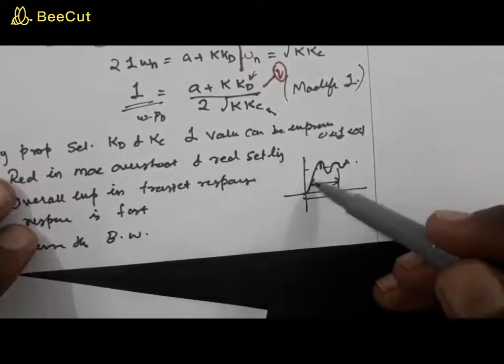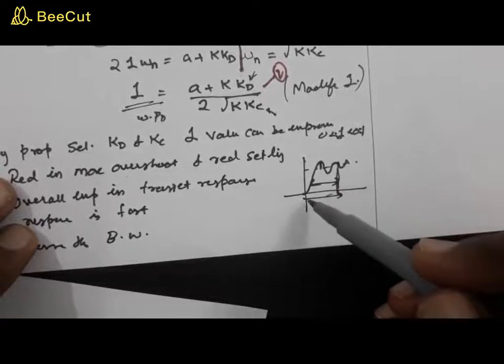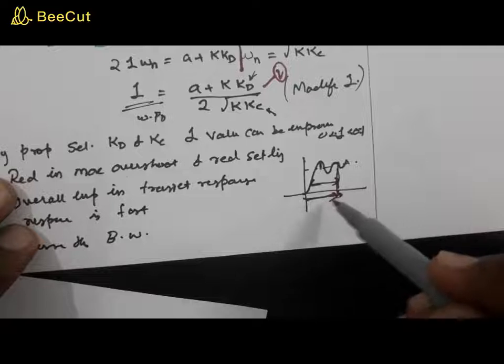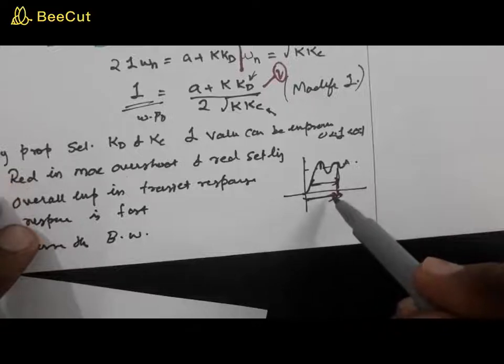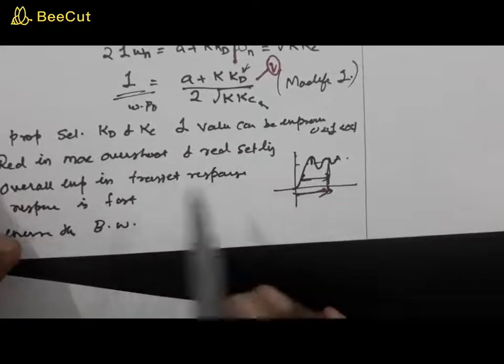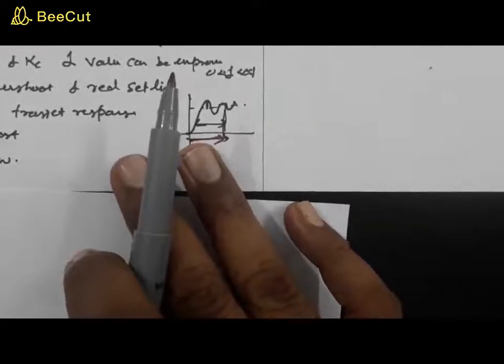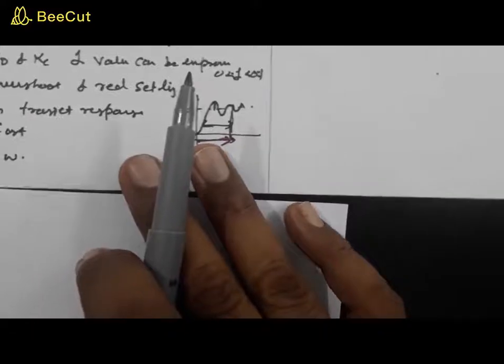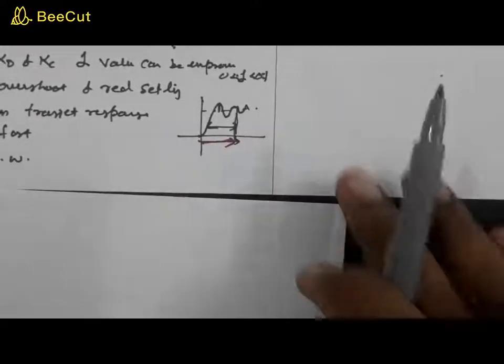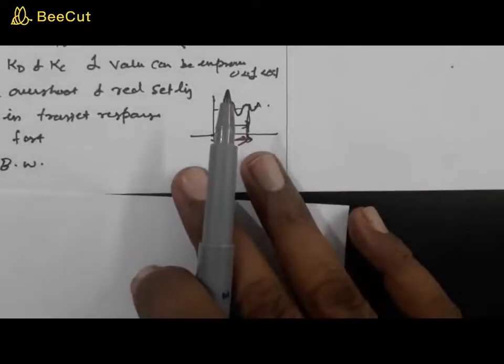Now, we have already seen the second order system like this. The settling time gets reduced, which means it gets faster. Now, the overall improvement is there in the transient response, because of the derivative control. As we have seen when we studied proportional and derivative individually, the drawback of proportional is that it is sluggish or lazy, while the derivative enhances or makes the response faster.